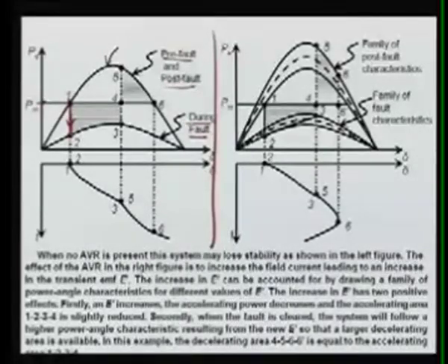So what will happen now, this will go and it is escalating, meaning delta keeps on changing with time. It is reaching point 2 here, in the delta; lower is the delta curve with respect to time, this is the power with the delta curve. So you have reached here, and now your fault is cleared. Once the fault is cleared, this curve will jump to 0.5 because the post-fault condition is similar to your pre-fault condition. So it will follow the PE curve of that top one.